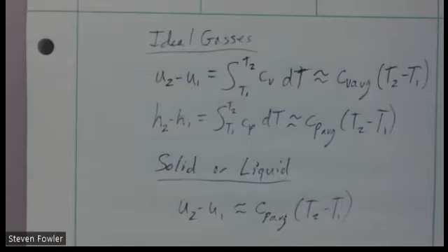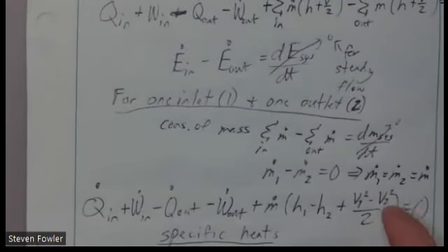We did talk about, in a control volume, it's not always obvious whether I need to worry about the kinetic energy change or not. How do we know if we need to worry about a kinetic energy change? Well, if it's a nozzle or diffuser, you have to worry about kinetic energy change. The purpose of those devices is to change the kinetic energy.